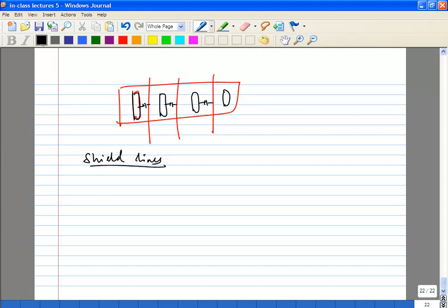So let's say you have to route a long way. So let's say from your VCO to your mixer, or from your VCO to divider to your mixer. Okay, so you can have very long lines. So first of all, let's say it's like this, and let's say this is your divider. Let's say this is 1 millimeter, something like 1 millimeter.